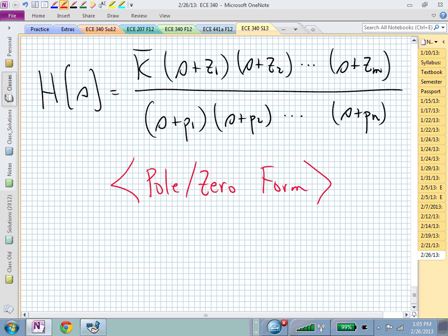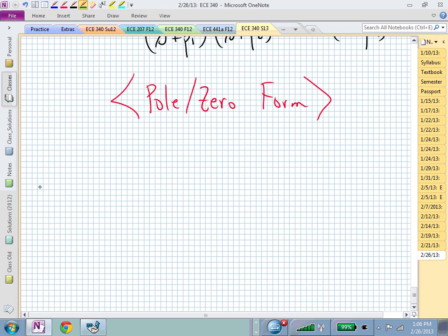However, when we're doing Bode plots, having all of these P's and Z's by themselves messes things up in terms of the overall gain, and we'd have to redo the gain calculation all the time. To avoid that, what's nice to do for sketching the Bode plot is to force all of these constant coefficients to be 1, to factor all of those out. For the Bode plot, we need the time constant form.